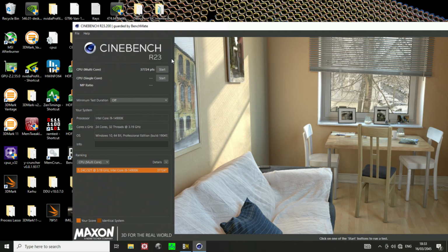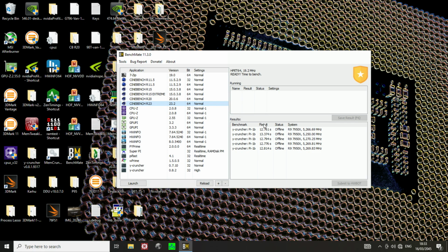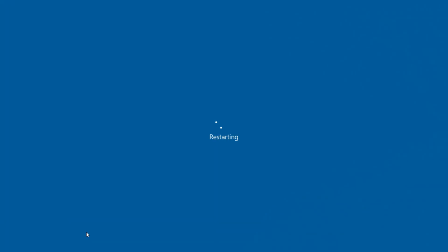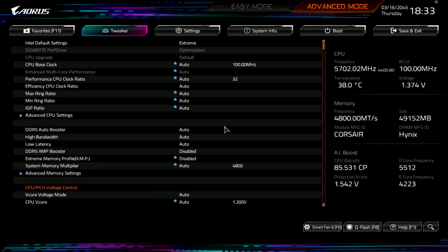So yeah, that didn't really boost the score very much, because when you have the AC load line properly matched to the motherboard load line, it is technically going to send a slightly lower vid request, so you do get slightly more power and thermal headroom, but it's not going to be the same as just setting a minus 100 millivolt vid offset. It just isn't. We might have shaved off like 20 millivolts.